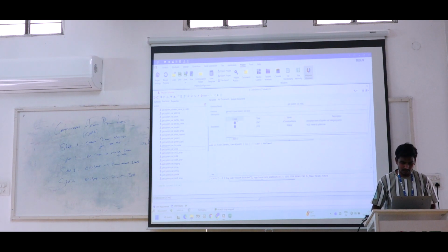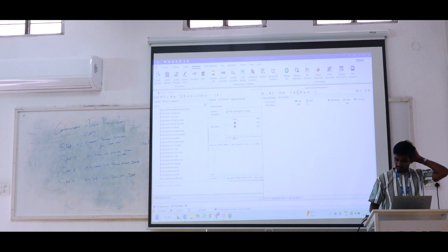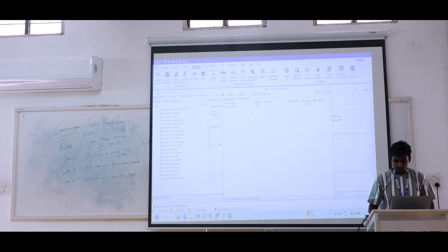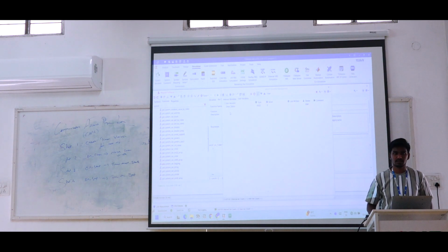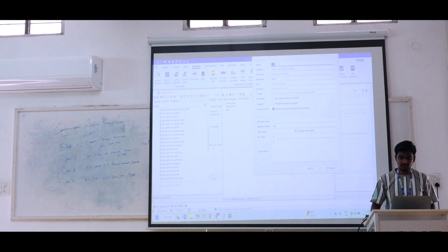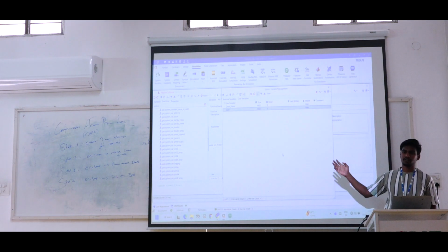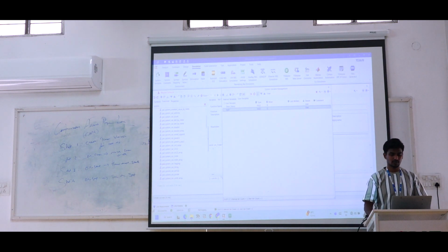Just scroll. It carries the API documents. You just select this and you find the API documents. So the description is get integer 32 type of system variable values. Before that, in the simulation system variables, if you don't have any, just go to system variable, right click, and use create user variable. You can just try variable 0. That is enough. Values by default are taken as 0 to 100.